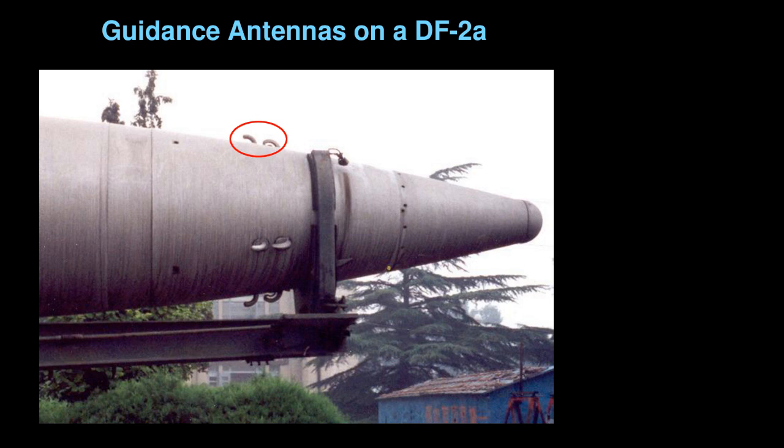More typically, what you do is you have what are called inertial systems. Accelerometers can be put on to sense both the rotation and the acceleration, and you can have an onboard computer that integrates those to calculate the speed and the location along the trajectory. You can either have what are called strap-down inertial, which means accelerometers that are fixed to the body of the missile, or you can have what's called a stable platform. So you have a platform with gyroscopes, and as the missile starts to turn, the table keeps its orientation in space, and the amount that it has to shift to keep that orientation is interpreted as telling you something about the operation of the missile itself.